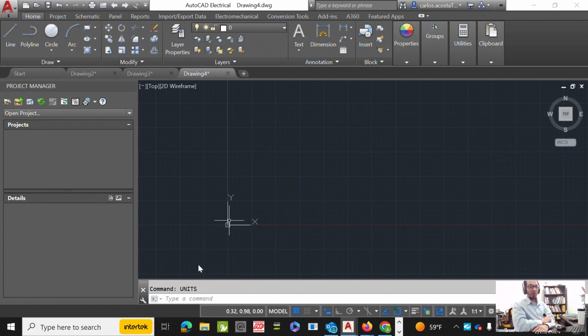There are tolerances that are very high, plus minus a quarter of an inch, right? So those types of things are for heavy duty wearable things, etc. We'll go into those types of things later if we need to. But that's for tolerances. It's for how much we want our part to vary from the nominal value because of the machining or the manufacturing techniques that we're going to use.